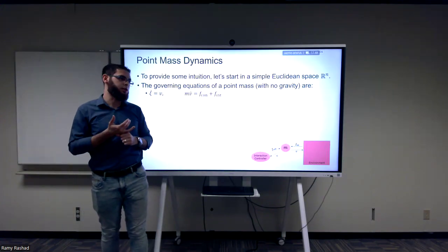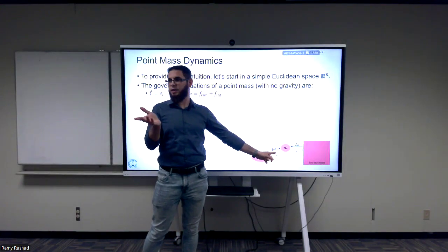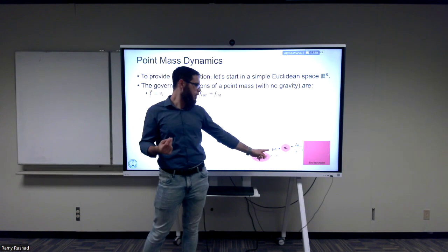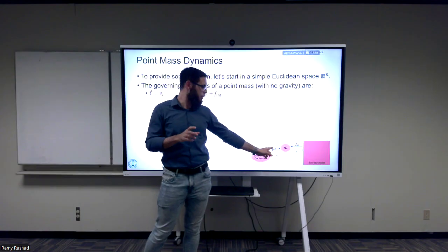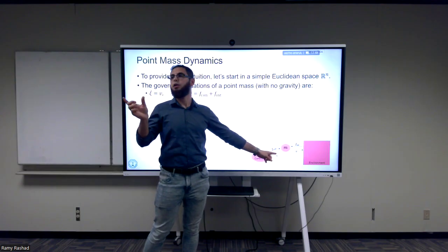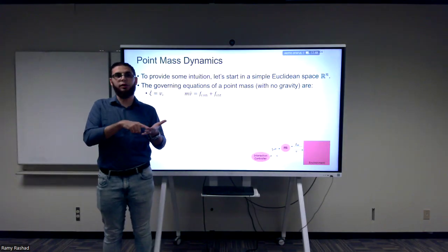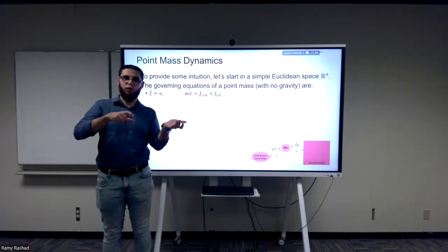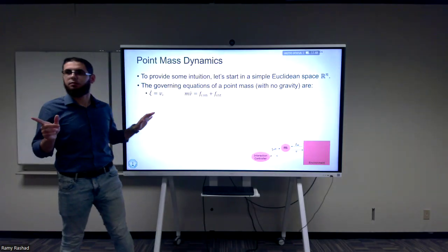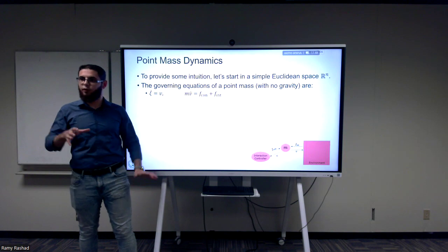There is also the power conjugacy, in the sense that when you pair these two, they both live in dual spaces, right? So one is a covector, one is a vector. So I can always take the pairing between them. What do I get? I get a scalar number. Whenever you take this pairing between the force and the velocity, what are the units that you get? Power. You get mechanical power. So this is the duality that we're looking for. This is also the same duality that we have between voltage and current in the electrical sense. What does it give you? Electrical power also. Are the velocities in this case different? No, the same velocity. The velocity of the body.